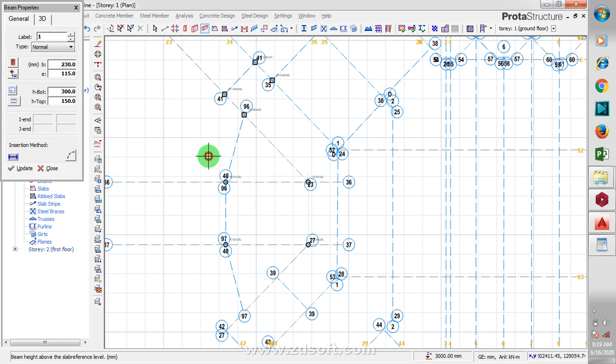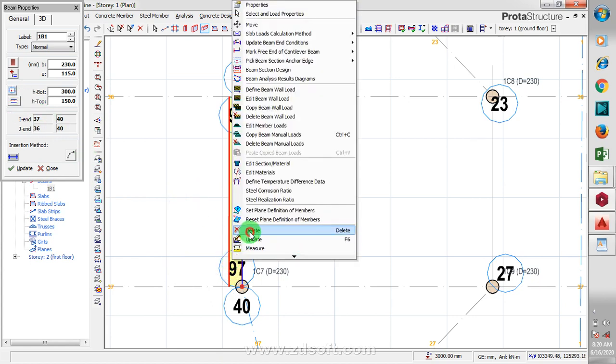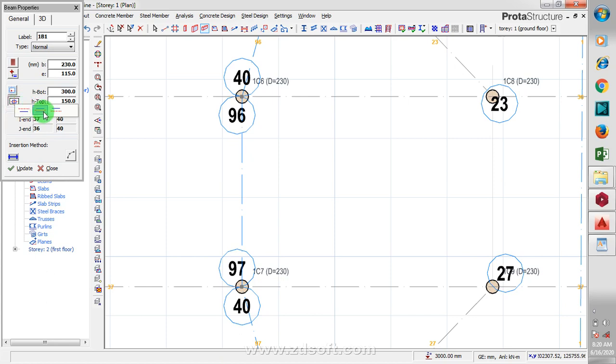There is this particular option here. I'm going to insert, let me insert my beam. If I drop it here, you can see the beam is on this side. That means I have to change this setting here. Click here, you can see this is center. Centralize it, and I pick again and I drop.